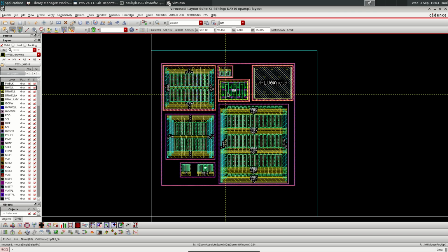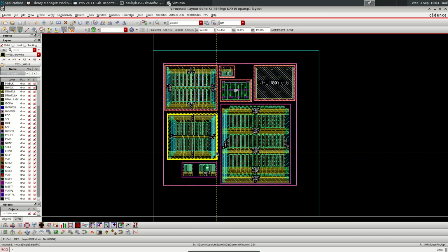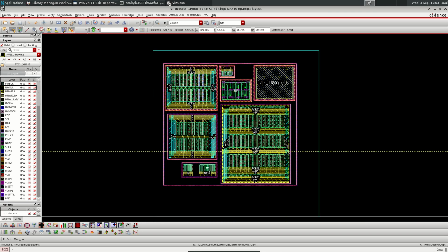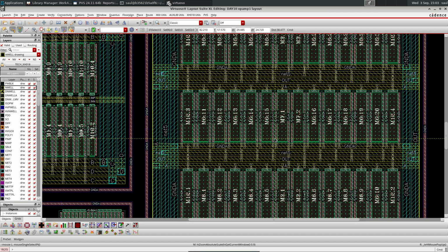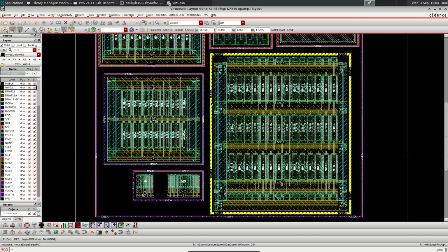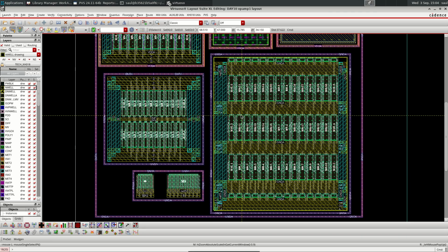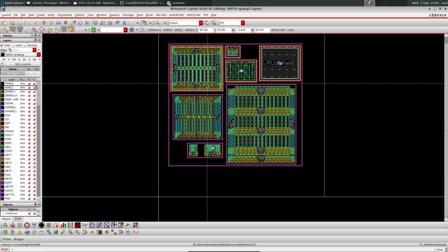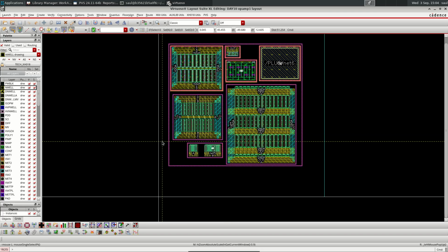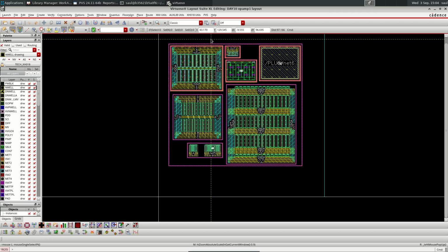I have rotated this resistor, and then I have just made this modgen without one of the trunks, without two of the vertical trunks, but otherwise it is exactly the same that we have done before, just slightly different routing for the modgens. At this point, we have everything ready for connection. We're going to do it now.